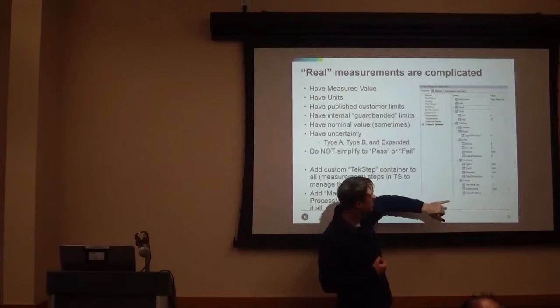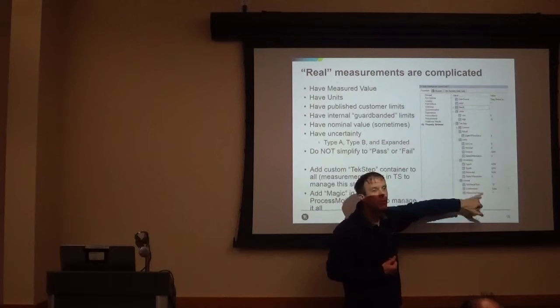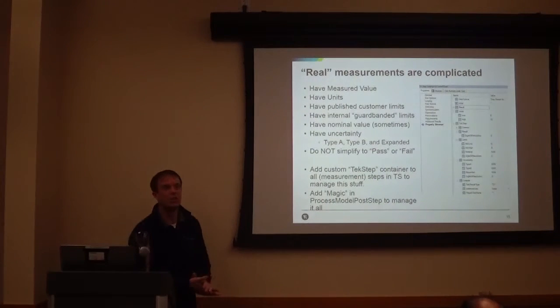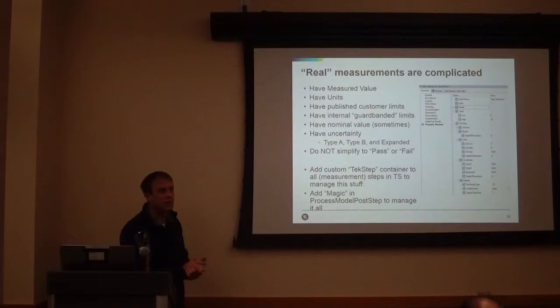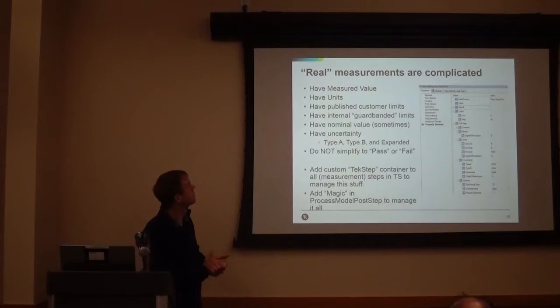For simplicity's sake, we just ended up having a Boolean for being in the indeterminate zone that gets added on to the general pass-fail status, because overloading the existing pass-fail status with TestStand was going to cause too many other problems.